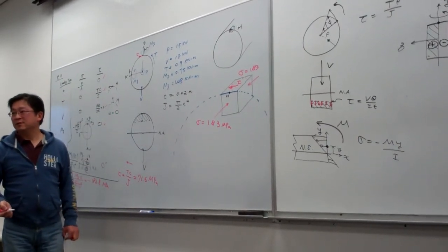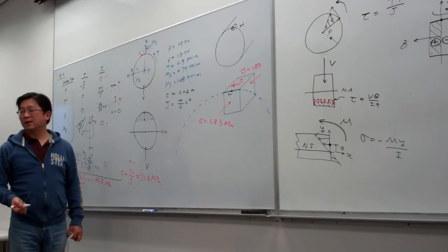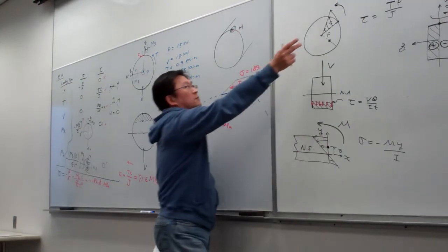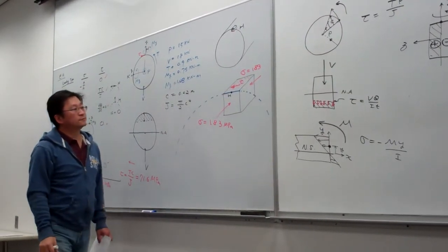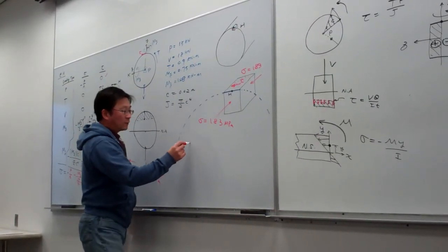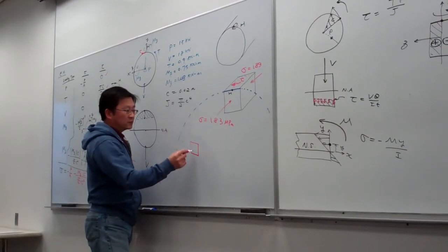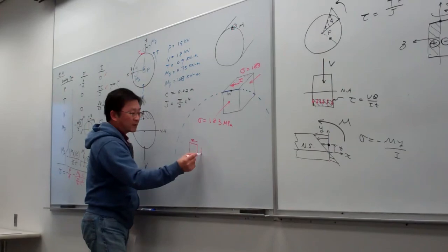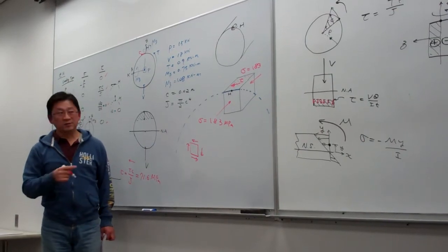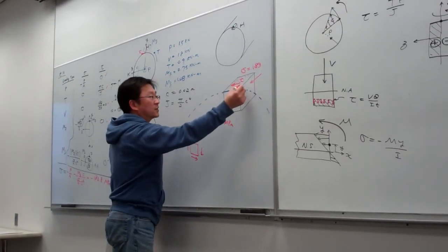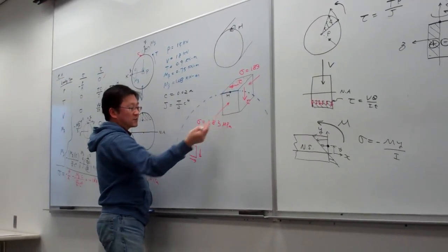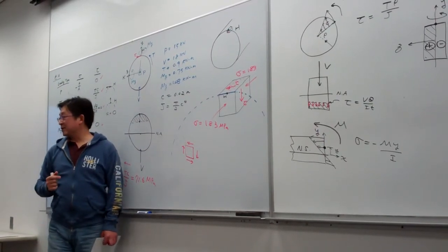What values let us know that it's going left? How do we know that it's going left? Because of here, I'm showing here. Okay. And then using our chapter 1, we know that if this is the 2D element, and we know the tau like this, then on the other three sides, right away we know in equilibrium the stress must be here. So given tau is like this, on this side the tau should be here, and on the opposite side and the bottom side, you can draw the direction like this.